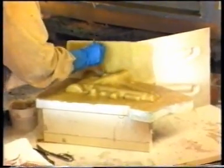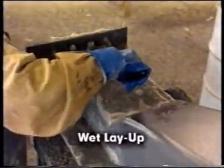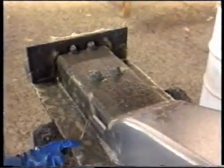More reinforcement material and resin are applied as needed in this manner until required part thickness has been built up. This so-called wet layup method can be used with nearly all reinforcement materials and is widely used to produce glass-reinforced polyester products and sometimes glass-reinforced epoxy products. Wet layup is also used for making composite molds.